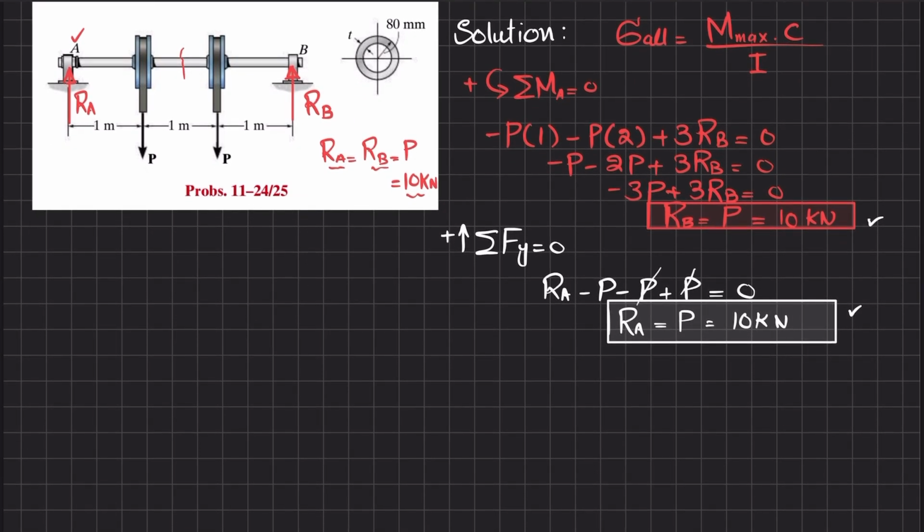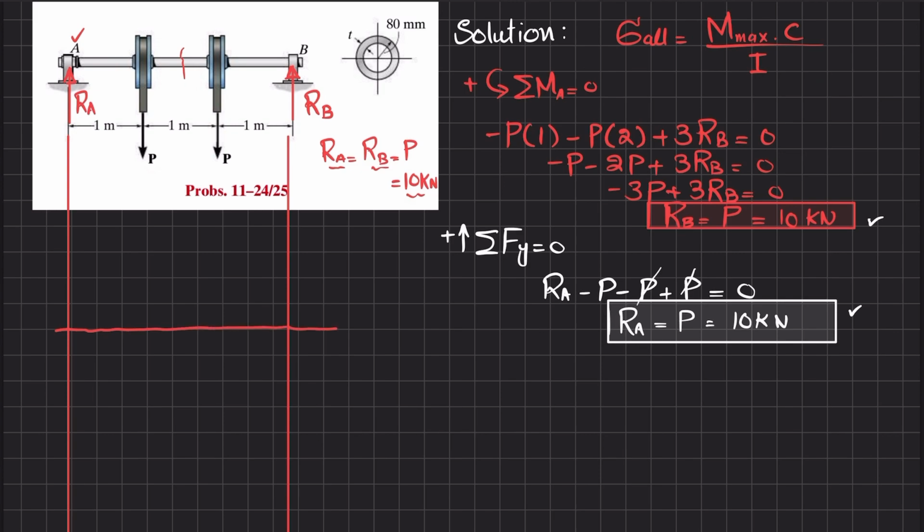So what we will do is take the vertical lines from the ends of the beam. Similarly from here you will take the line, and then there is a horizontal line to show the length, x, in meter. Here you will have the shear force in kilonewton.